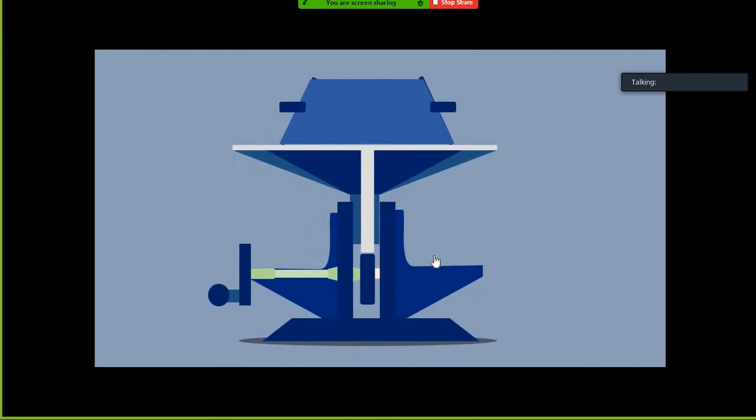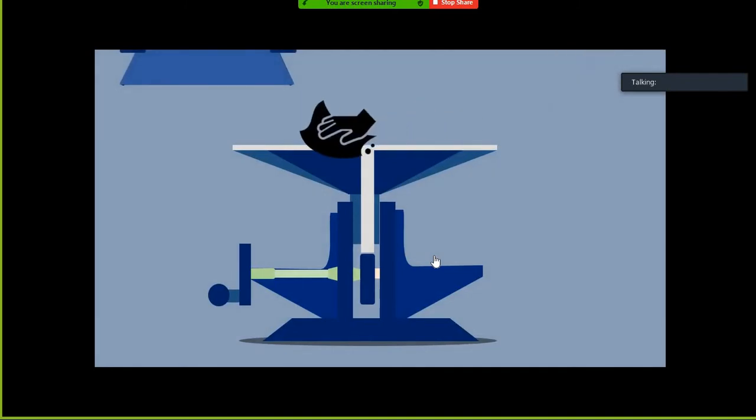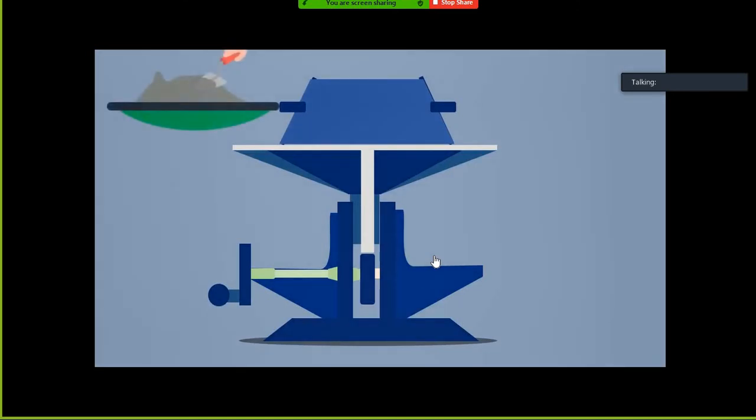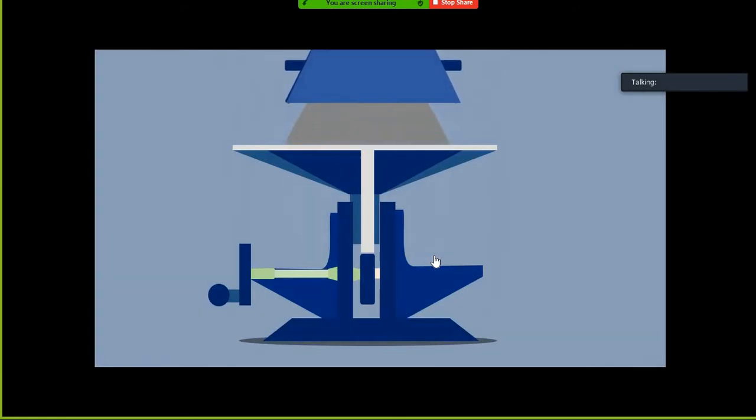Let's now see the step-by-step procedure to do this test. The tabletop is cleaned of all gritty material and is wetted. The mold is placed in the center of the table, firmly held, and is filled in 2 layers. Each layer is rodded 25 times with a tamping rod. After fully filled, the excess concrete is leveled off. Now, lift the mold vertically upward. You will notice concrete stands in the shape of the mold.